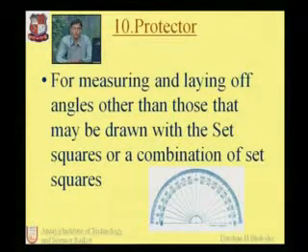If you want to draw inclined lines of any degree, by keeping the center point on the horizontal baseline, we can draw from 0 degree to 180 degree from the right hand side to the left hand side, and similarly from 0 degree to 180 degree from the left hand side to the right hand side. So on both sides it is possible to indicate angles.